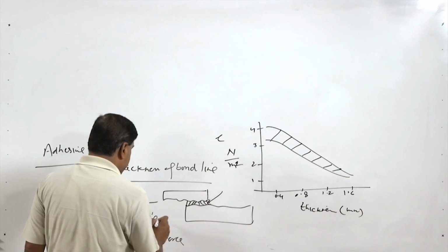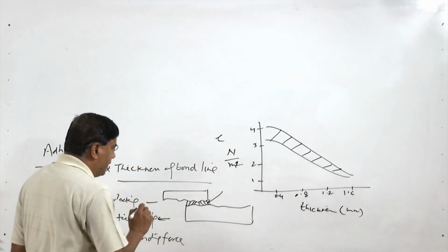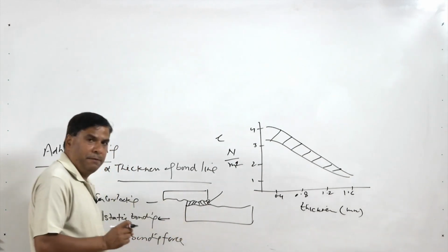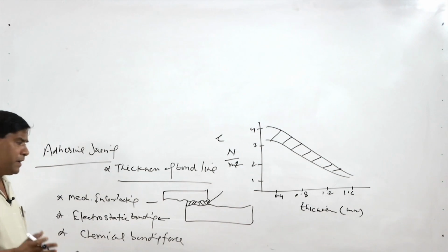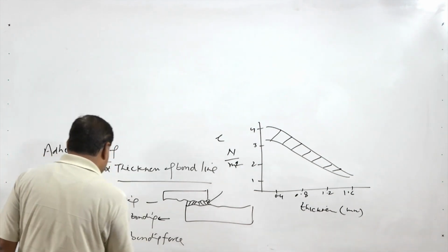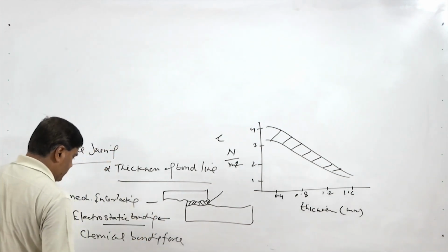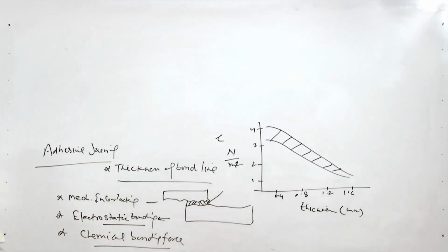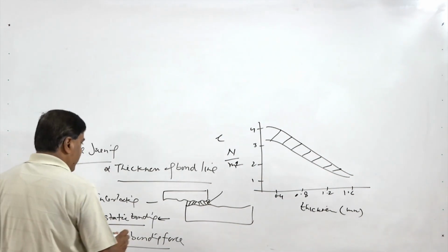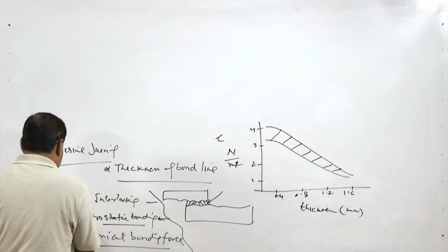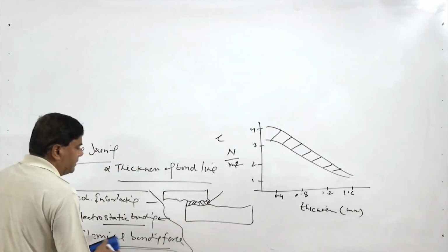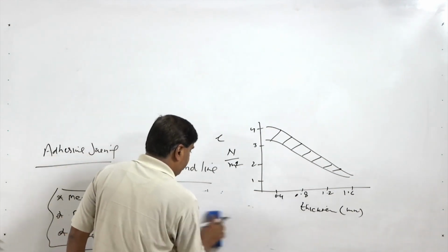And electrostatic bonding depends upon how different the electronegativities of the adhering materials are, which in turn will be determining the electrostatic bonding force, and the kind of chemical interactions between the adhesive and the surface of the sheet taking place. They will be determining the bonding force. All these three mechanisms may be overlapping, and in turn will be determining the joint strength.